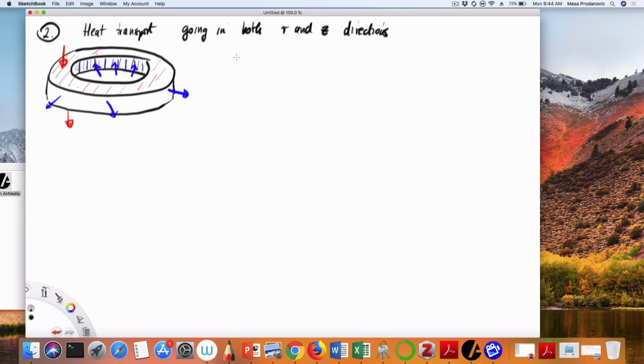So my vector e is 1/2 rho v squared plus rho enthalpy plus tau dot v plus q. So I got to balance these vector components going in through radial and z directions.